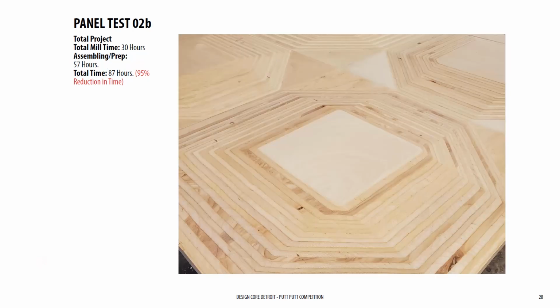And finally, we started looking at different materials. So MDF, there is an issue with MDF, and this is going to be outside. MDF has a nice clean finish on top. So when you get rid of that nice clean finish, it's exposed to a lot of humidity. It's going to start to swell. It could start to deform. So to minimize that, they always had to put a clear coat right on top of it right away.